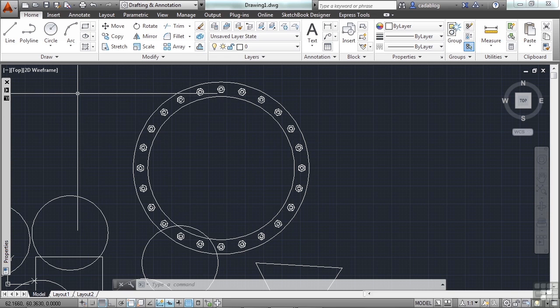There are some other palettes available, but their complexity goes way beyond the scope of this video, and we are going to look at some of them more closely later on. But suffice it to say, the palette is another format of a window that you can interact with inside AutoCAD. They can be rearranged in your drawing area, they can be docked or locked into position, or they can just float around and you can move them as you need to. They can hide themselves or they can stay open. You can right click, and remember, pick up on the right clicking here.